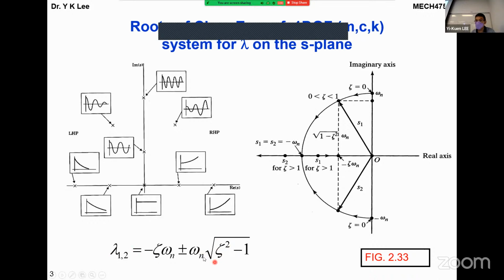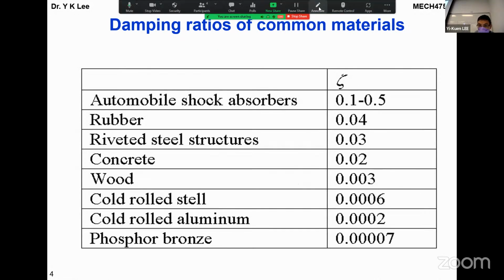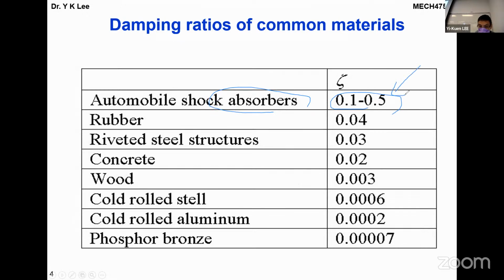This one, our damping. Damping is something important. That's why in your homework we try to introduce this kind of vibration isolator or vibration damper, right? Using some polymer material like TPU, like this giant company's product, to make sure that we can really achieve some good performance. So this is something I think is useful. And again, in homework number 2, the typical sharp curve shows the damping ratio is high, to make sure that you can do vibration control, right? If you look at metal, damping is so small without this kind of polymer, like what we show you, TPU, and in this case PU. PU is a very common material.